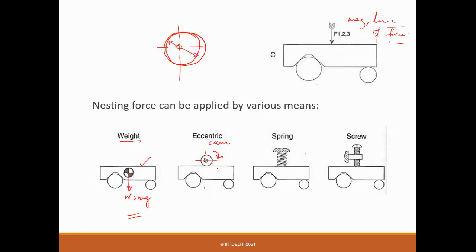So wherever you need some force quickly, you have this eccentric cam and then mostly connected with some kind of lever, so that you apply a force, you can easily lock and unlock it. So this is one possibility. Another is you just put a spring. Along that point, because of this spring force also, you should be able to provide that.